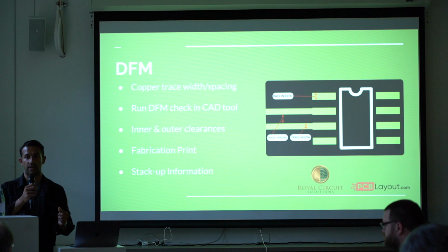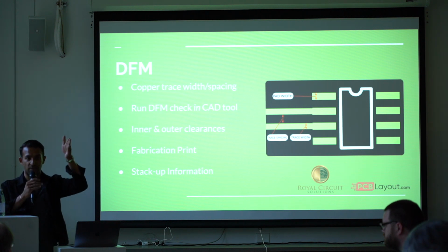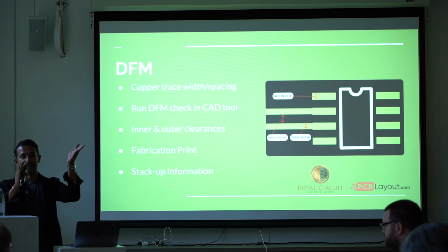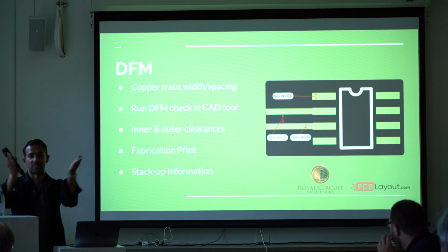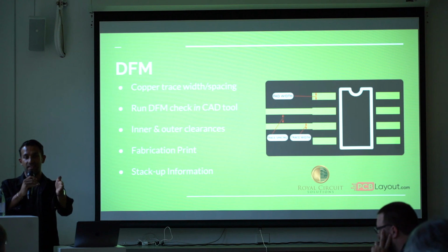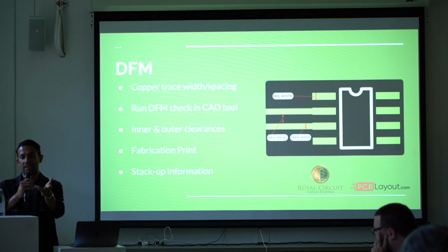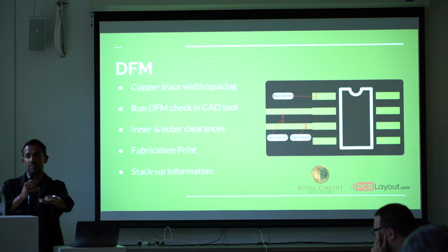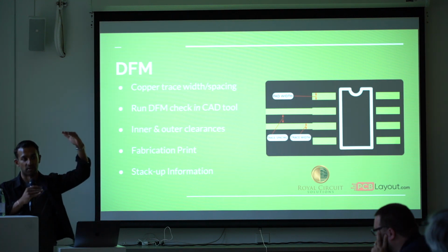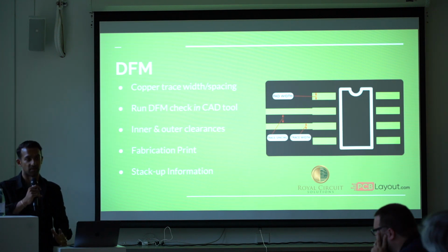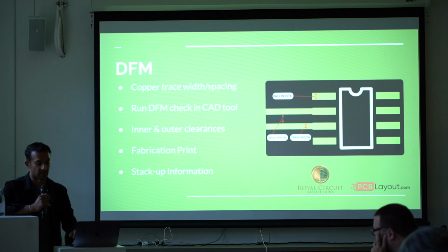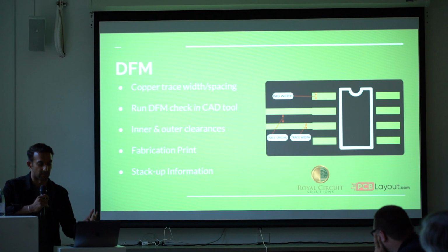And the reason for that is when you etch a board, it's not etched perfectly vertical, it etches like a trapezoid, kind of like this. And so if you have 2 traces right next to each other, it's going like this, and then at the bottom of that layer, they'll show up together. So you need to have enough clearance for it to go all the way down, and you have the clearance in between. And the thicker your copper, the more distance it has to go, the wider that angle when it etches. And so you need to have some sort of clearance, which is why as the copper weight increases, so does the minimum clearance required for your trace spacing, as an example.